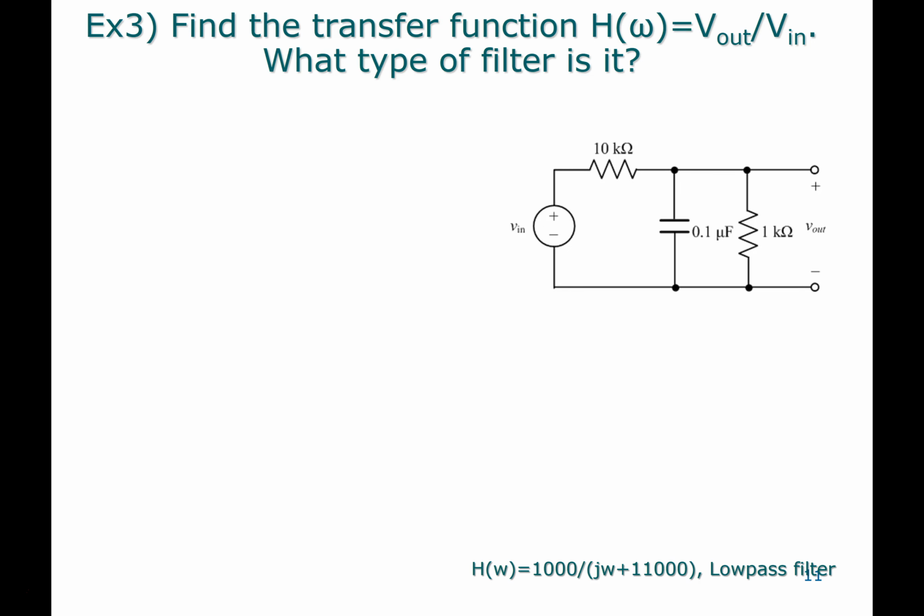You might be given some random combination of R's and C's, and you can solve that. It's really just a question of finding things in the right form. This is kind of a grinding one. I don't know if you find this very interesting. Let's just sort of set it up. To set this up, you would say, well, okay, so ZC is going to be 1 over j omega C.